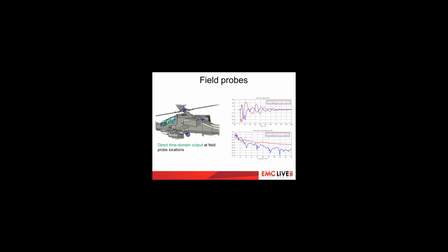And you can see that the ringing in the time domain is related to electromagnetic resonances. And these resonant frequencies are inversely proportional to the dimensions of the aircraft structure. So a bigger aircraft produces resonances at lower frequencies. For example, at 6 megahertz, the wavelength is 50 meters, a half wavelength is 25 meters. So if the aircraft is a multiple of a half wavelength, it's matching the wavelength, and this produces the resonance effect.